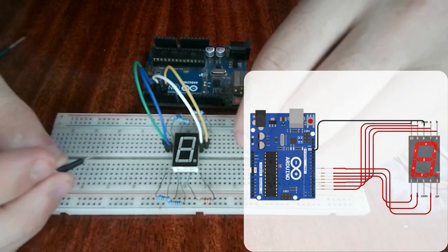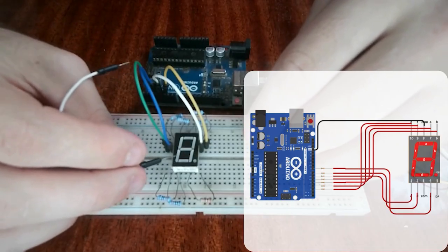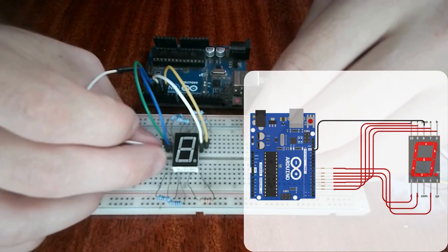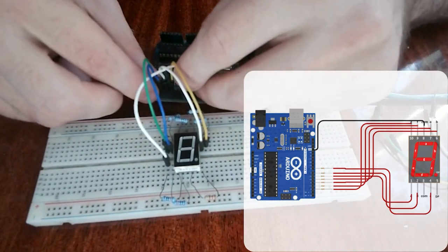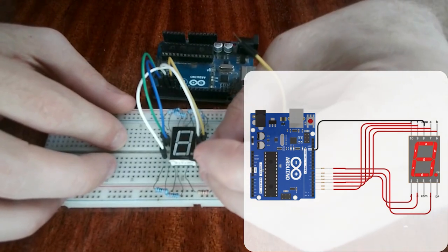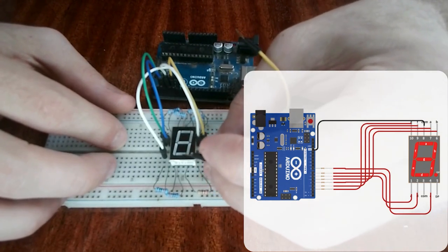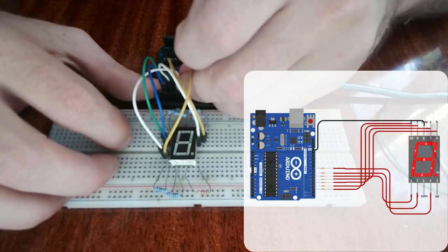Now we're going to connect the E pin, which is right here. This pin is responsible for this LED right here, and it's going to be connected to pin 6 on the Arduino. Then the D pin, which is right here, is responsible for this LED right here, and it's going to be connected to pin 7 on the Arduino.